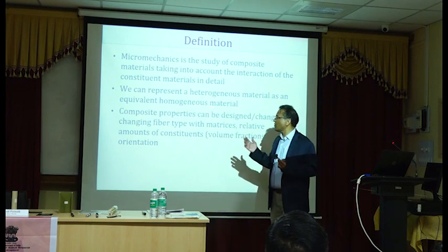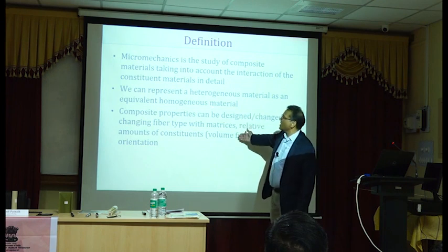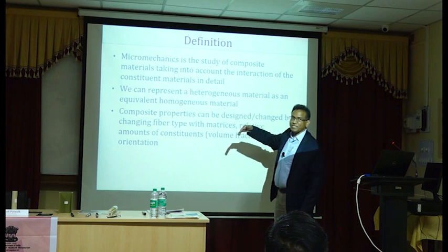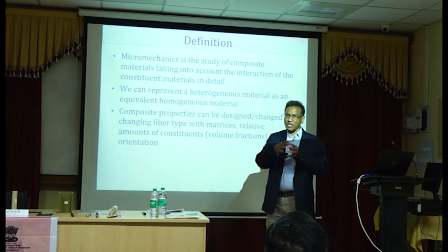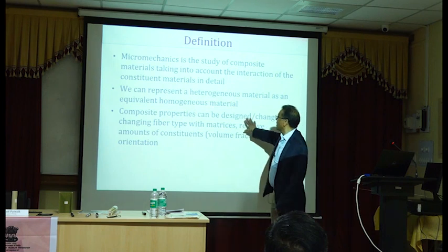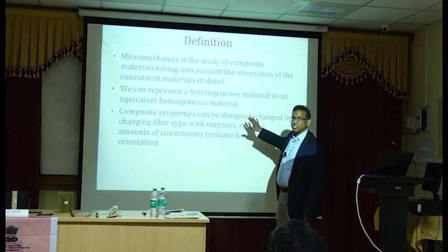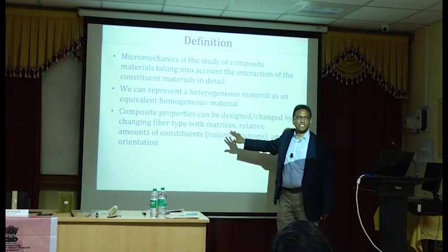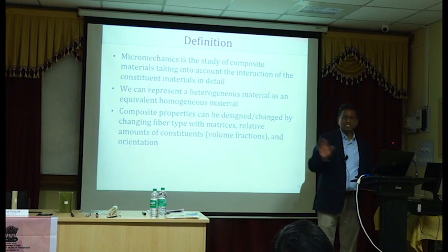So if you change the fiber amount, the properties will also change. So you can design your component based on the requirements, based on the amount of stresses you need to carry in your composite, and therefore we can use micromechanics to do that kind of design. Does it make sense? That's the basis for micromechanics. Is this clear to all of you?